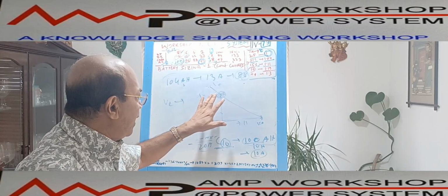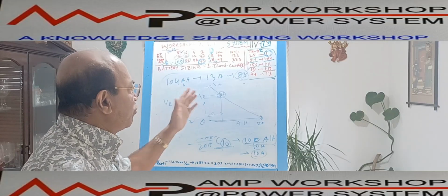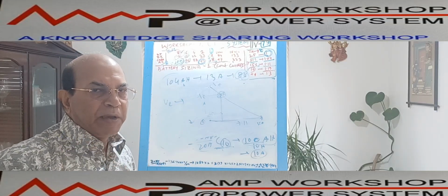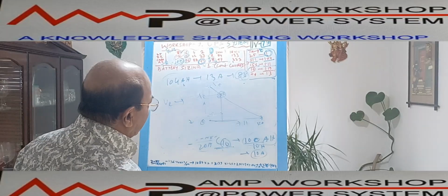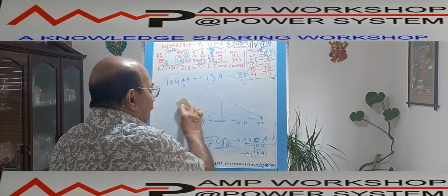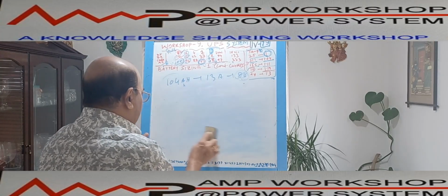So when I am ending the voltage at 90% of the nominal voltage, most of the manufacturers have to declare how much ampere hour I can draw from this rated condition. Most of the manufacturers say normally up to 80% of the capacity.